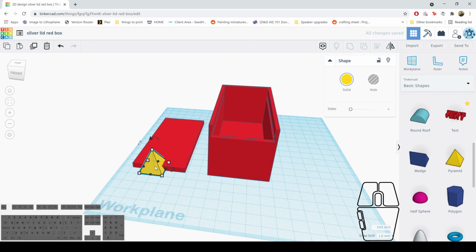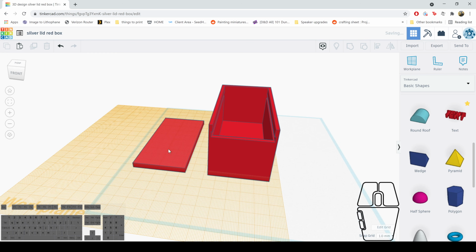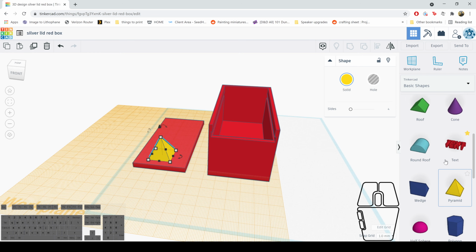So if you want the whole shape to rest evenly on top of the lid, you would just use the work plane, which you may remember, the button is over here, or W on the keyboard. We would place this on top of our lid. And so now when we drag out our pyramid handle, you can place it in the middle there, and we get the whole object evenly resting on top, and then we can group it and pretty much be done with it.